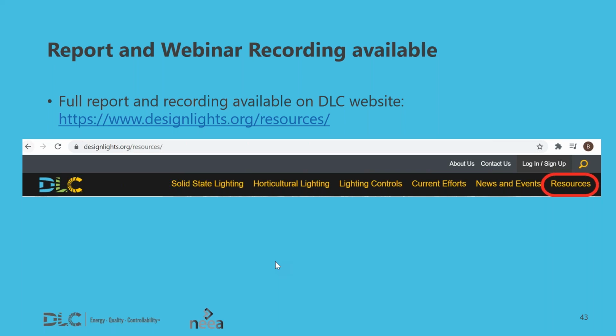And this control typically is implemented during commissioning or startup, and it's not to be confused with personal control, where the person can use the wall switch or dimmer, or in some cases some sort of remote control to manipulate light level, and that is considered to be personal control or personal level control. But high-end trim is determined typically by the designers or by the electrical engineers at the beginning of the deployment, the startup and commissioning process.